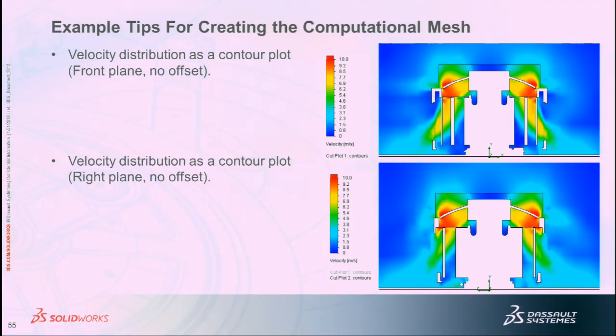And this is typical of a rotating region. Here is the angular velocity, and you can see how there is some discontinuity because you have an angular velocity body force term in the equations, and in the next cell right outside the rotating region you don't. So that's inherent, that's a limitation in using it.